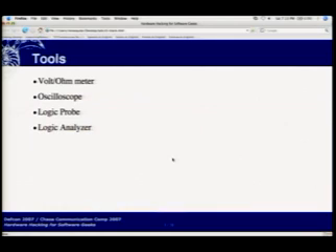So these are some basic tools that I use in doing hardware work. The volt ohm meter is basic. If you don't have one of these, chances are you're not really doing a lot of electronics. An oscilloscope, a little less basic, but if you get one, you will not believe how useful it is, and you'll never really remember how you lived without it. Logic probes and logic analyzers are both for working with digital logic only, and a logic analyzer is a little expensive. Logic probes are very simple. I'm going to go through these.